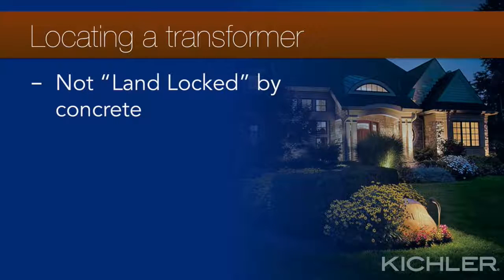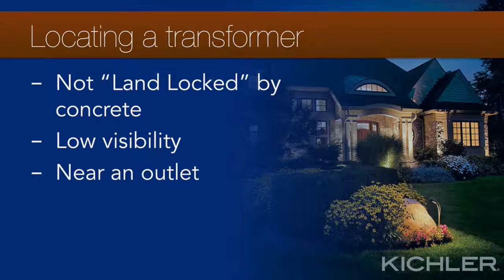Don't mount the transformer above a sidewalk or driveway unless you have a plan for carrying wire into the landscape. Number 2, low visibility. And number 3, the location is near an outlet. The transformer should be in a low visibility area near an outlet.